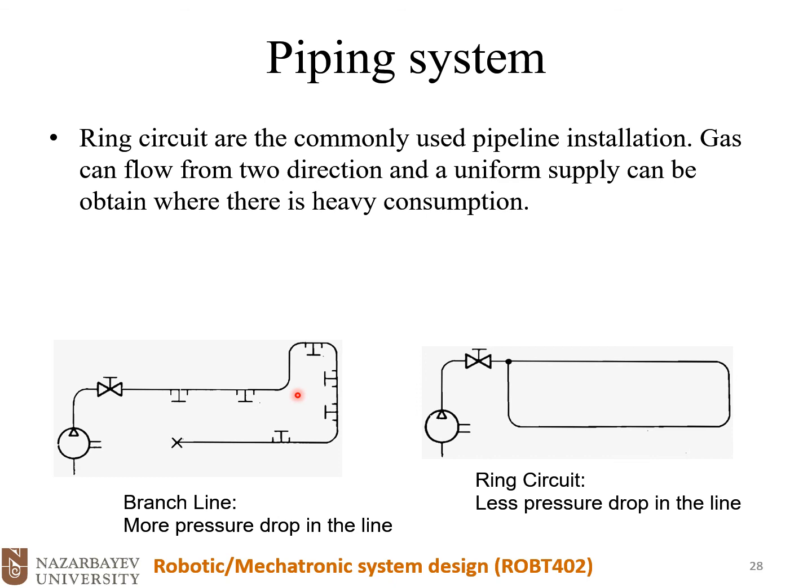Anyway, even if you use a drying unit, the water will be concentrated. And we need to accumulate that somewhere in our system and drain it from our system. So it's good to have a gradient of 1 to 2%, and then we should have a draining valve to drain the water.